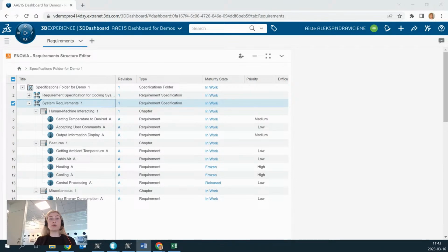In such a case, I recommend customizing the requirements on the CATIA Magic side. This requires creating a profile, a stereotype with the required custom attributes, applying it to requirements, updating the mapping schema, and then, of course, synchronizing once again to get those properties into your SysML model.